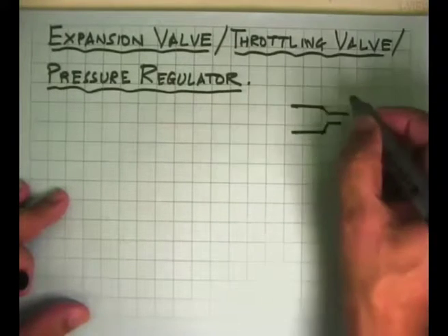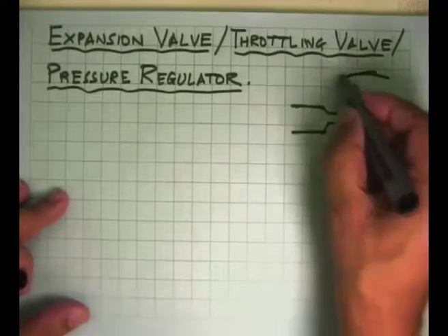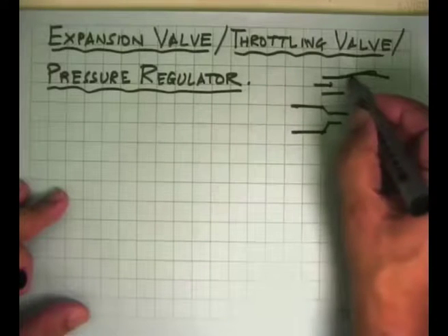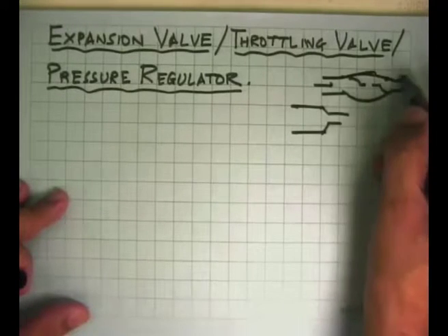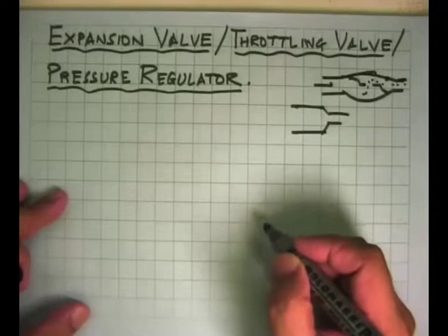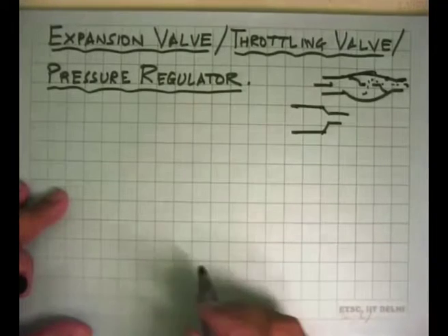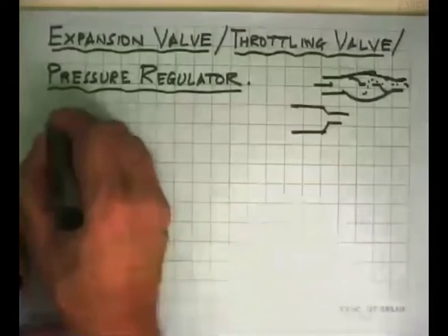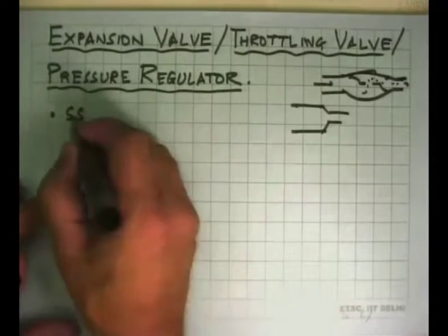and this flow could be passage through a valve, which means that there is a body into which it enters from one side and we have a small constriction there. As the fluid goes through this, there is a big pressure drop, and that all happens over at the outlet. This is a small device, so what one does is that we assume that this is a steady state system.